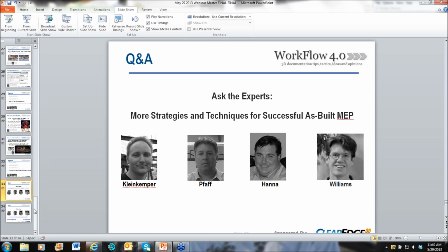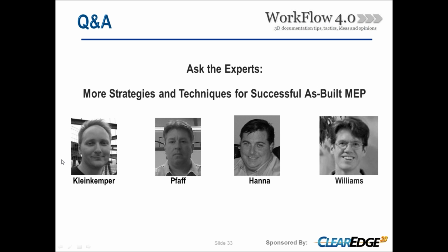We tie all that together with our survey control network, where we're locating some targets with the total station, and then we move up to the second floor, and so on and so forth. That's where we've found the most efficient, best results. We really have a lot of confidence that we're getting really good, tight registrations. We're trying to rely on the survey control network to help us do that.